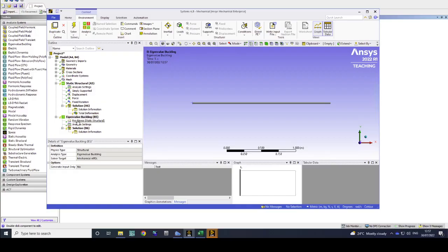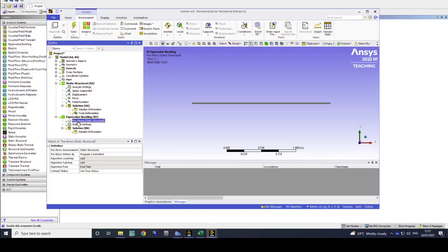So you see here, this is the pre-stress. Essentially, this is where what we call the stress stiffness matrix comes in. You can define from which stage of the static solution this should come. Sometimes static solutions may have several time steps, so you define one load and increase the load in different ways. But in our previous simulation, we had only one step, which was one step of loading to unit value. Hence, even changing this to time step or load step or time is not going to make any difference.